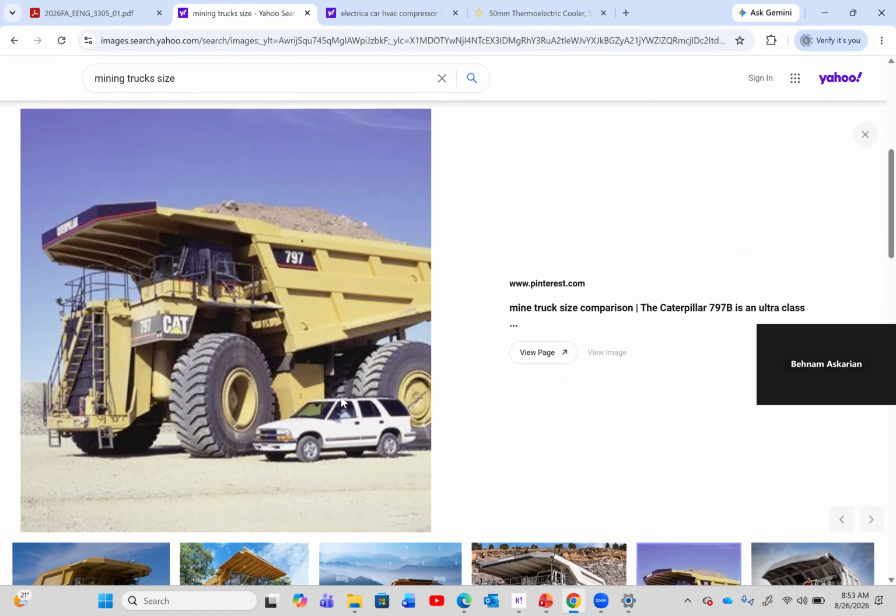In the front, there is a huge diesel generator, like a 500 kVA or sometimes 1 megawatt. And that is just for generating electricity. And in the rear axle, there are usually 1 or 2 large electric motors, 1 megawatt each or 500 kilowatt each. And they actually run the rear wheels. So this is completely separated. The front is for generating electricity, and it runs the electric motors.